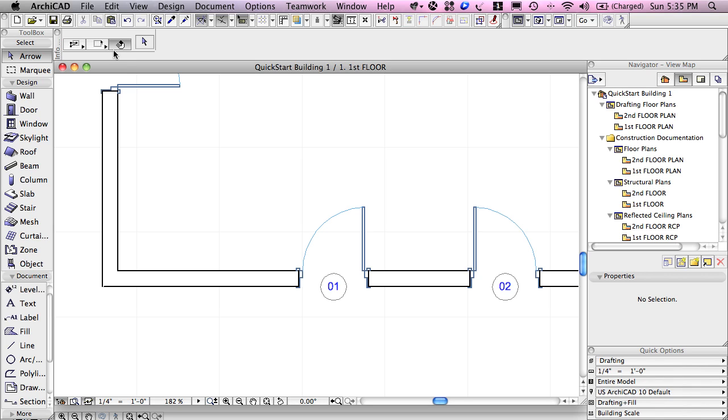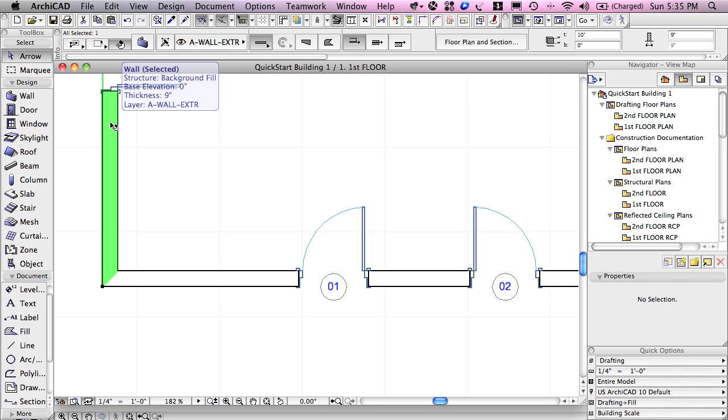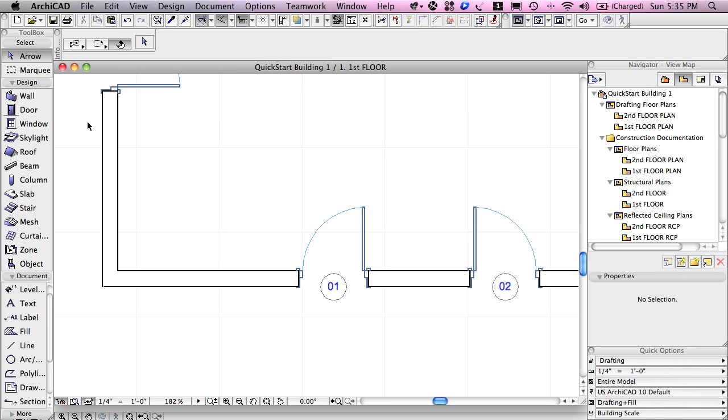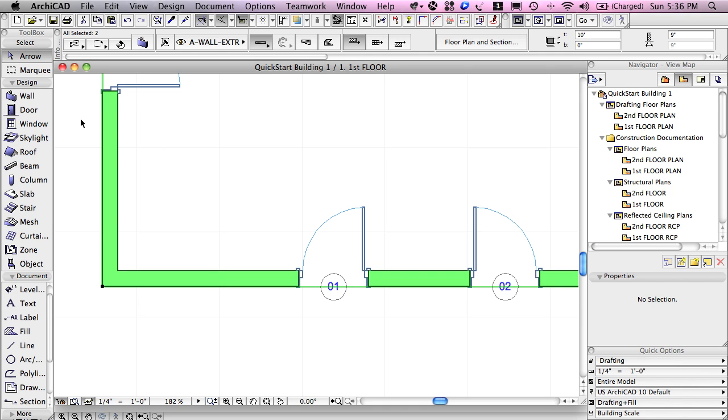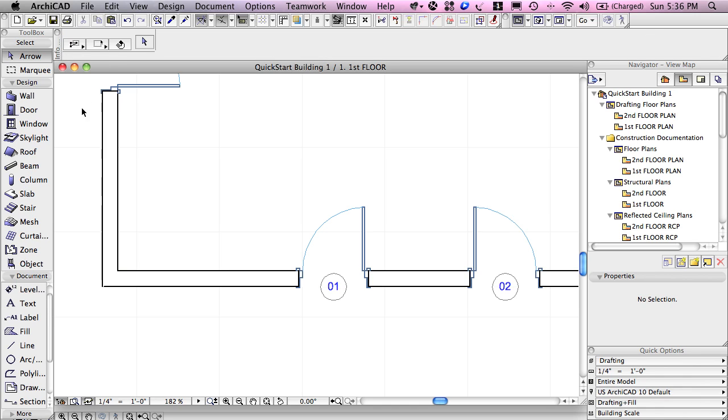There is this button here, the third one that you see. It's called Quick Selection. Now with Quick Selection, I can go, say, in the middle of this wall and click, and it selects it. But with Quick Selection off, by clicking that, then when I'm in the middle, you notice that the cursor actually looks like just a normal arrow. It's not sensitive to the wall. So when I click, I'm now drawing a box here without it sensing the wall right away.